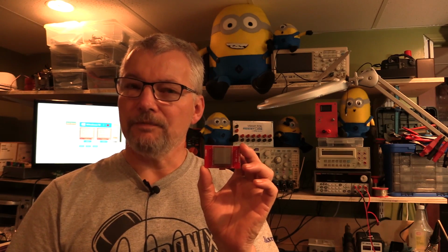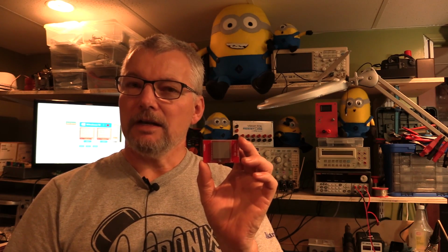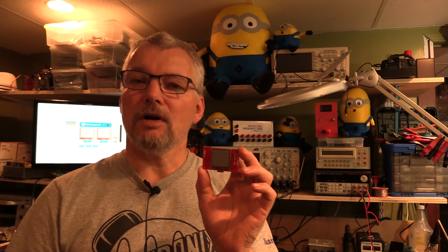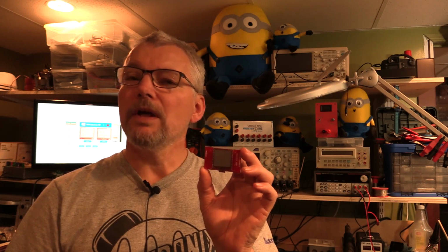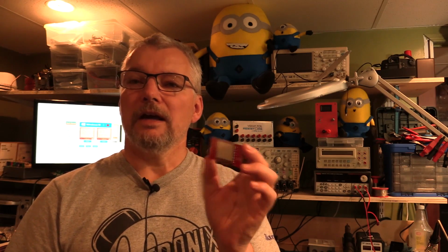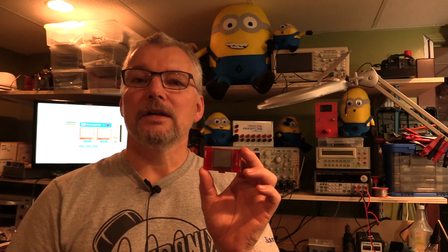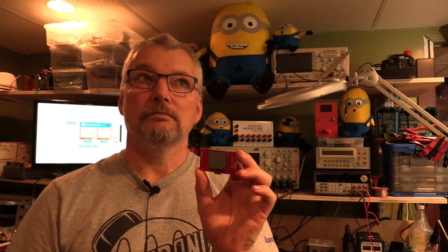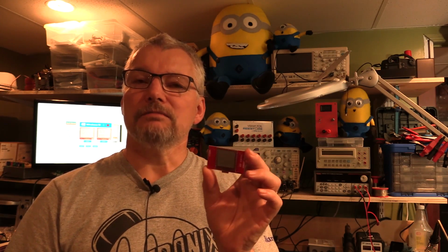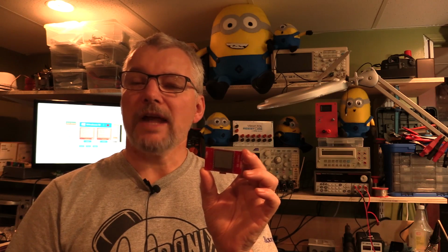And what I've done in my software is I've set up a 200 millisecond timer under interrupts that just calls a function to send out the command to alternate the what they call VCOM bit, and it's just a 2-byte command that gets sent to the display, and I'm just doing it 5 times a second. You can do it anything from about 60 times a second down to 1 or 2 seconds between them.